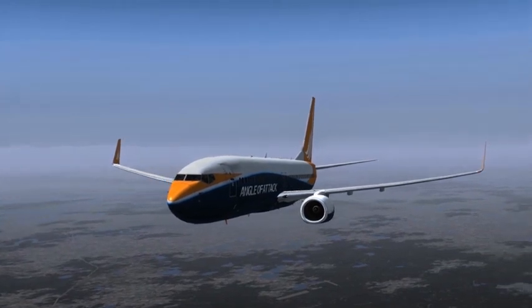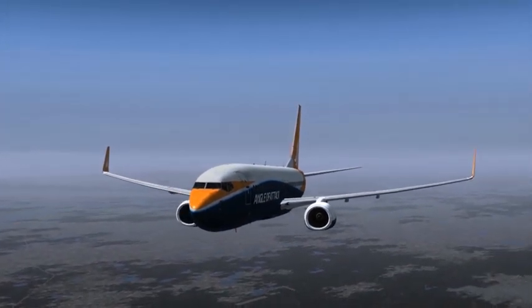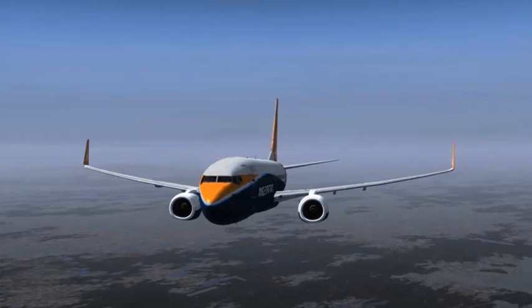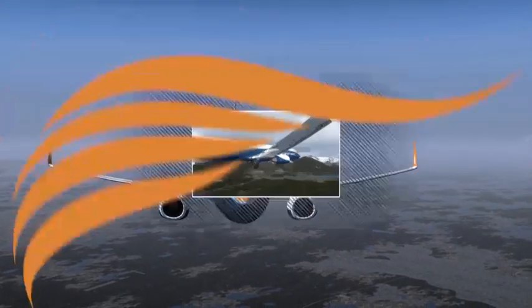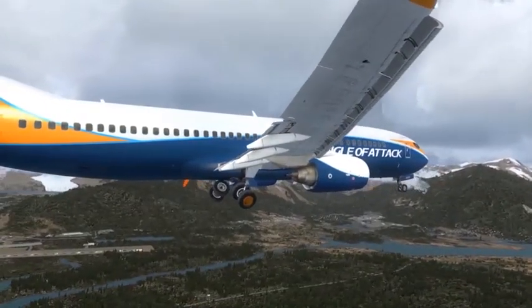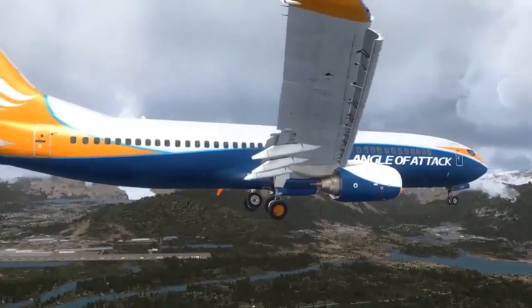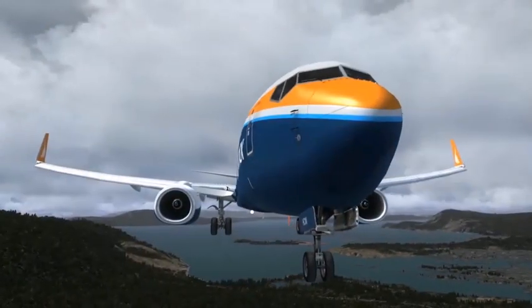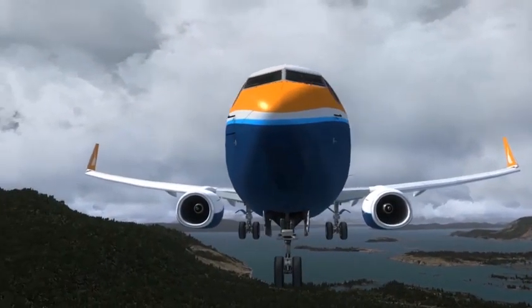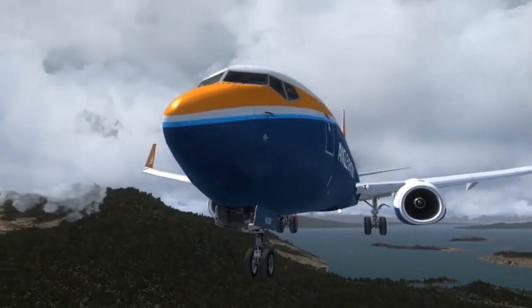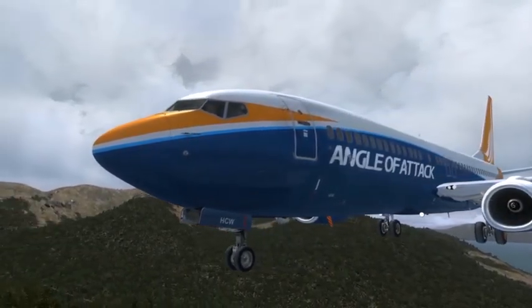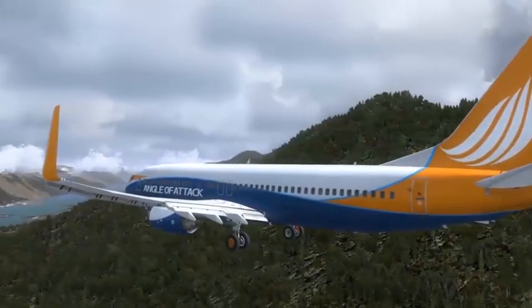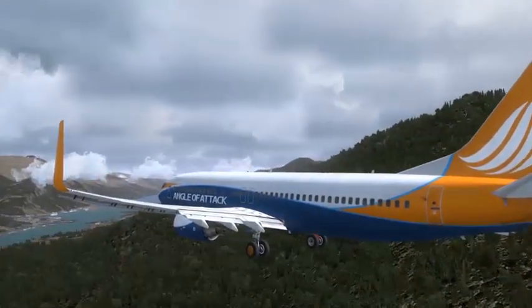20 minutes before landing, the pilots must enter the actual landing field elevation so that the cabin altitude climbs to that same value. Once the aircraft has commenced its descent and the external pressure increases to 0.25 psi or more than the flight altitude or cruise selection, the pressurization system senses the start of the descent phase. This is when the landing field altitude selector comes into the equation.